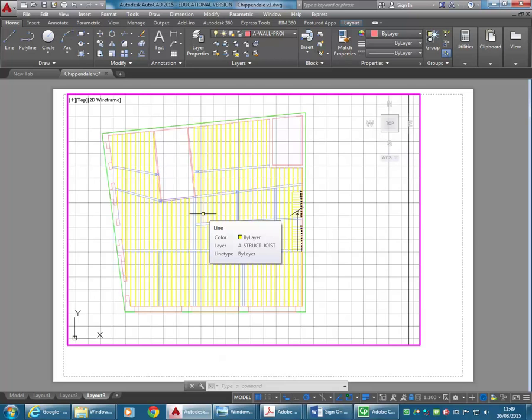That's right, it's painful, because then also, once you move it, so it's just this padlock next to scale. And so once it's blue, then it's locked. And yeah, I know how bad it is, because once you zoom and change the scale, if you forget to reset it immediately, you've lost the position as well. And it's a really nice thing you can do when you're setting up sheets in AutoCAD, is to have the plans in exactly the same place. So when you make your PDFs, you can flick through them and quickly see where the changes are.